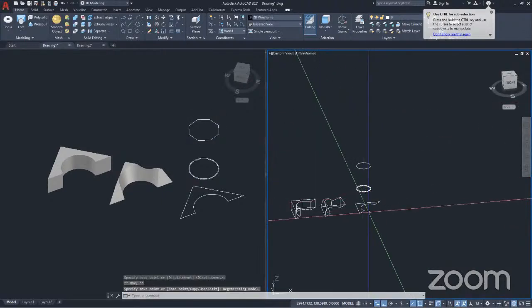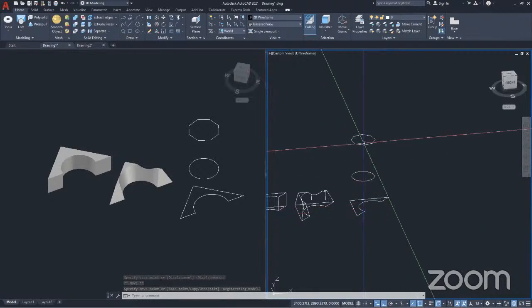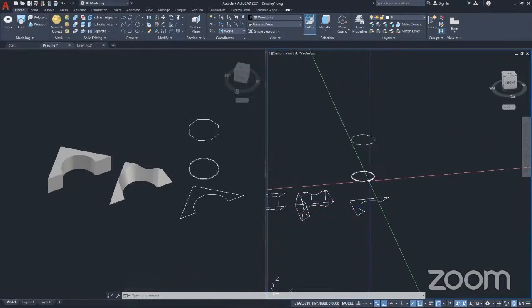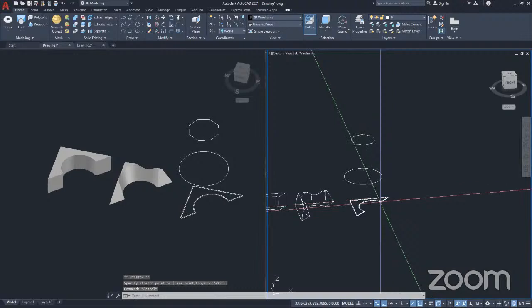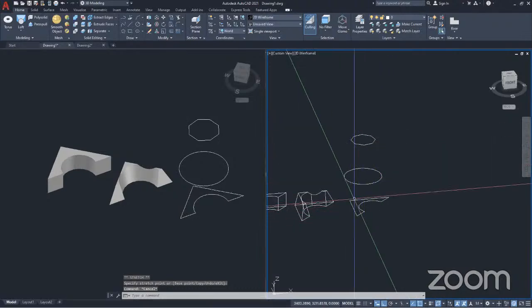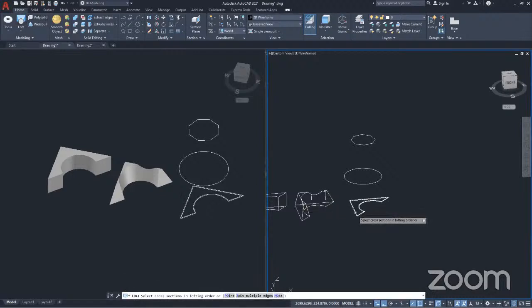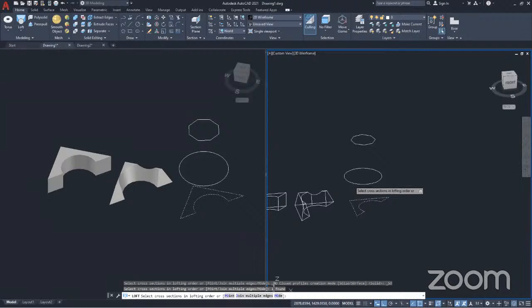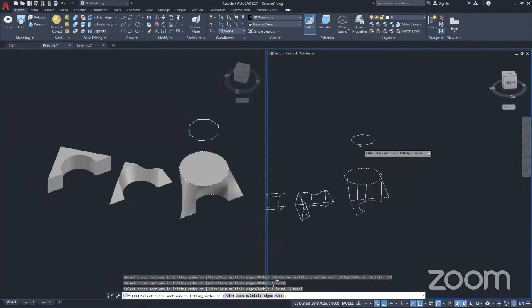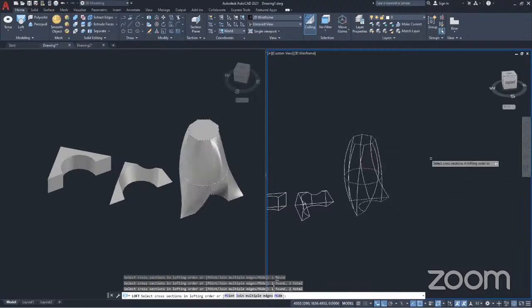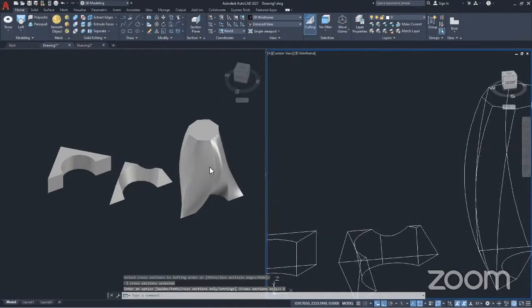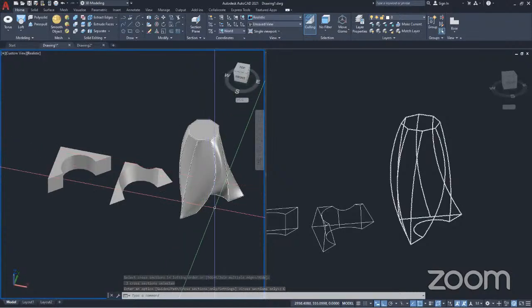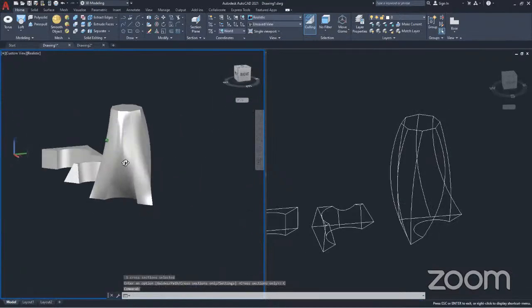Now, see what the Loft command will do. It will create a shape from these 3 shapes. And let me see something. Let me extend the size of this. Let me increase it. Okay, now it will create a shape combining these 3 shapes. Okay, now let's see. Loft. I'll select my first option, select the second one, and then the third one. And enter. First option only. Okay, so you see we have a funny looking shape, like so.